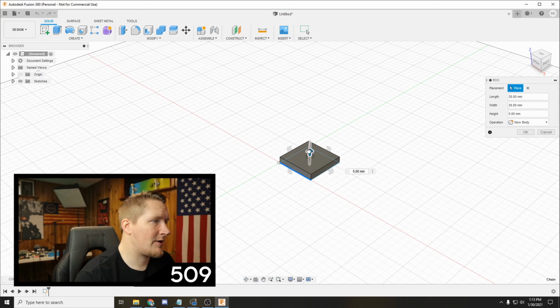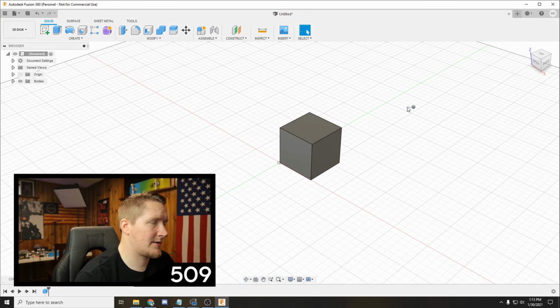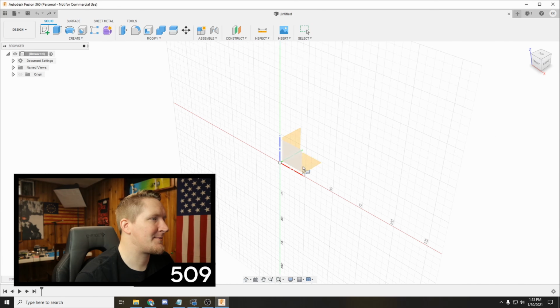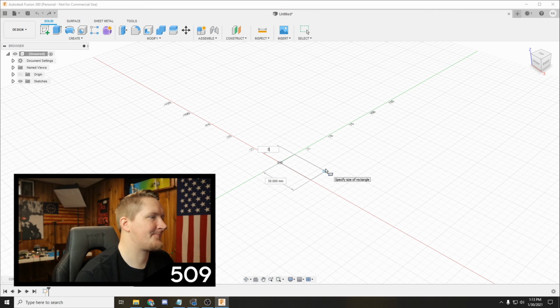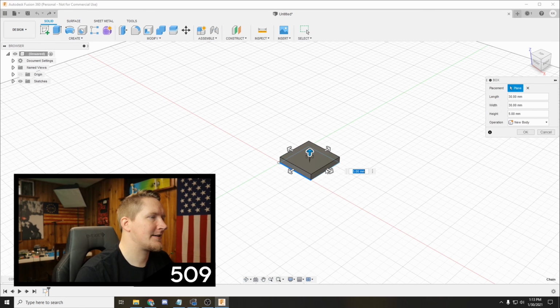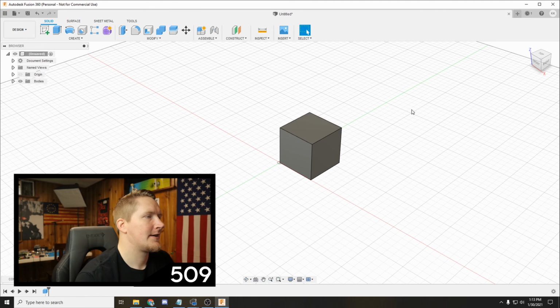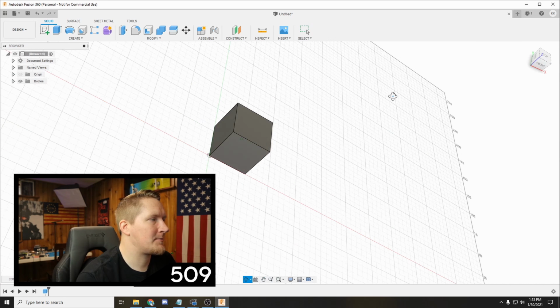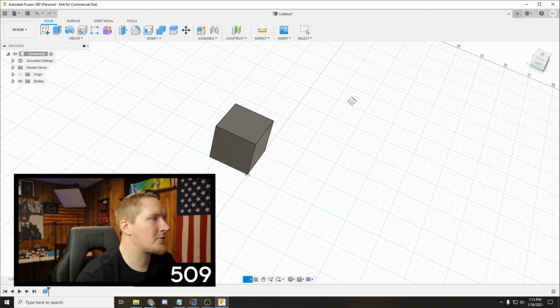And then it asks you how tall you want to make it. So we'll make it 30 by 30, make a perfect square. You click OK. See, I'm already trying to use the Tinkercad controls. And yeah, because I haven't used Fusion in a while. I've been busy making videos and doing other stuff. So anyways, here's our box.